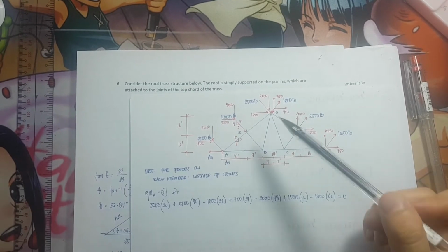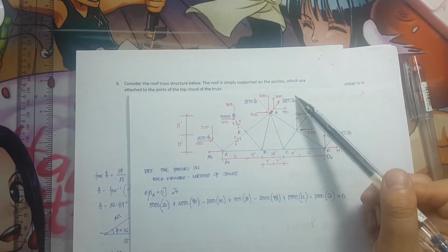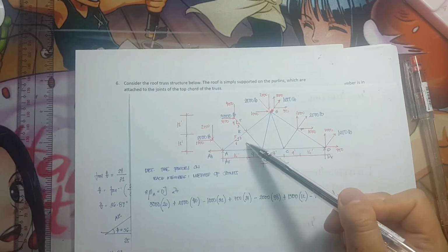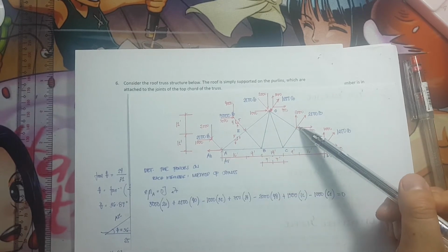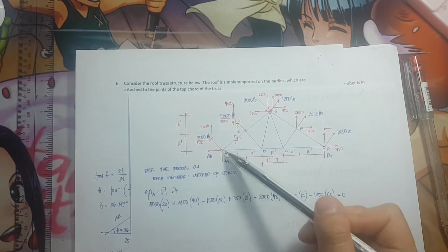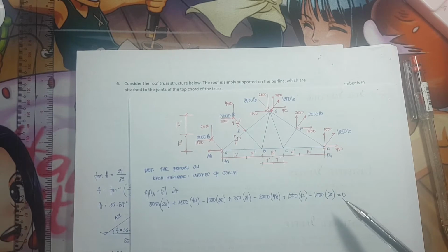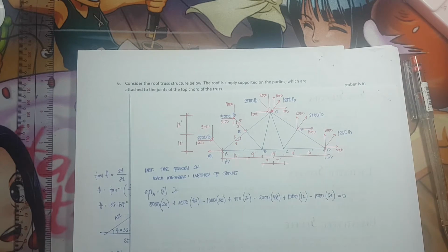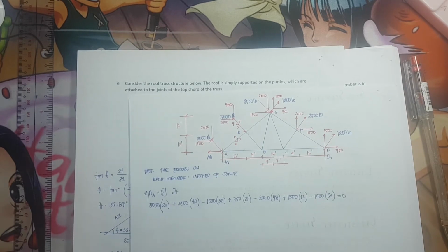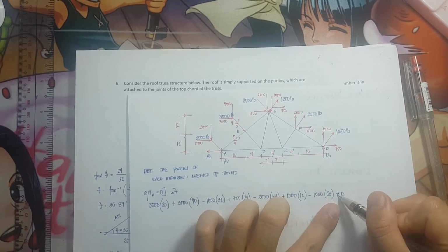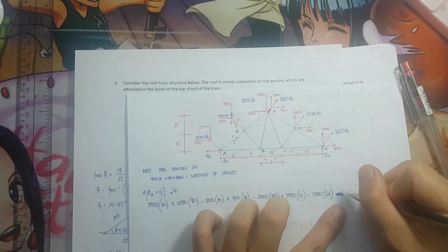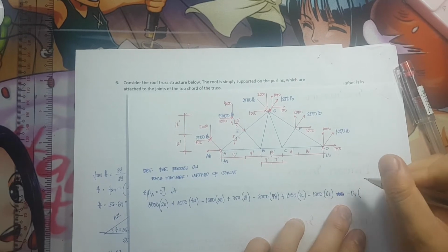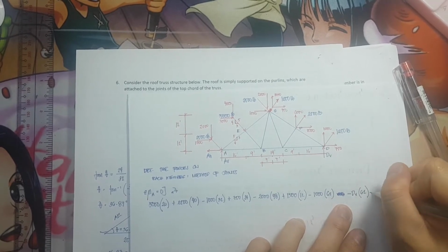I repeat, we can use naman the 1,250, the 25, and the 1,250 directly. It's just that we're going to get the perpendicular distance with respect to A, and that would be mahirap. So it's best if we can just convert them to vertical and horizontal component. Okay? And lastly, we forgot the vertical. The vertical rotating counterclockwise, so that is negative. The vertical times a lever arm of 62, and equate that to 0.